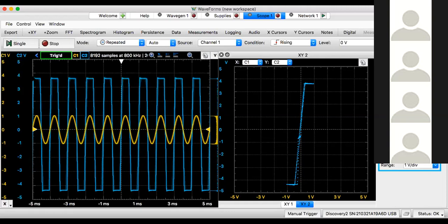What's wrong? The blue is, first, not a sine. Second, it only goes to positive 3.7 maybe, and it goes to negative 4.5, right? Negative 4.5. So that's problem number 1. Problem number 1, we call it saturation problem. Saturation.